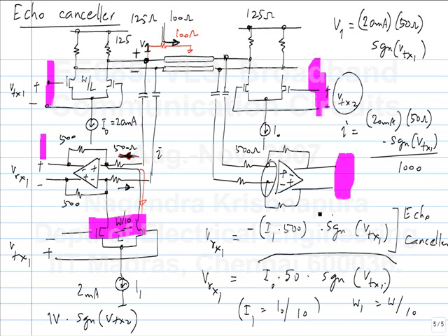So what are the practical problems with this? From this the cancellation is exact. What are the potential issues? Op-amp should, but okay, firstly it may not be an op-amp receiver. That's just a schematic. I could use a differential pair and do similar kind of cancellation. If it is op-amp based, then it has to work at high frequencies, but it doesn't have to be op-amp based, it's just one way of doing it.